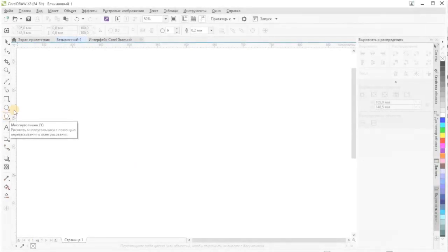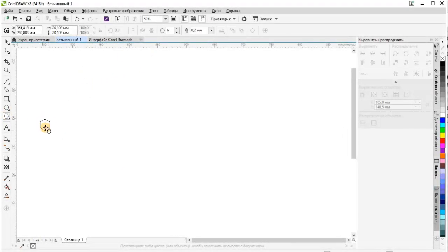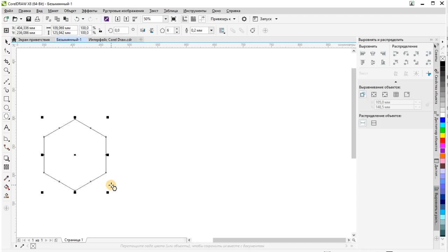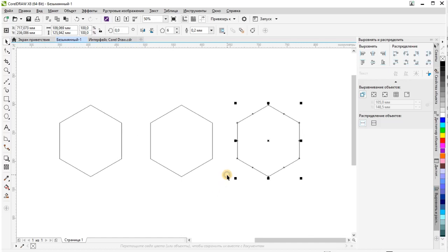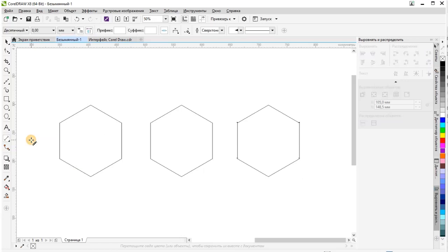Dimension lines. Selecting the Dimension tool on the Curve toolbar makes it possible to use not one tool, but a whole group of tools for drawing in the image various dimensional schemes, consisting of extension lines, the actual dimension line and the dimensional inscription. Dimension schemes and extension lines are composite objects of the following classes: linear dimension, angle dimension, and callout.